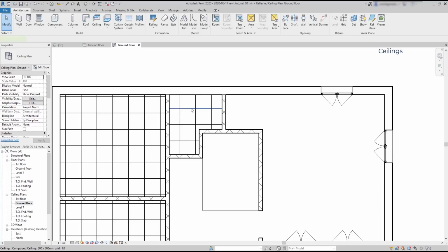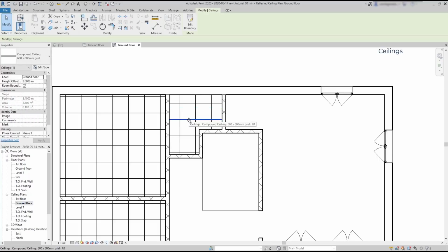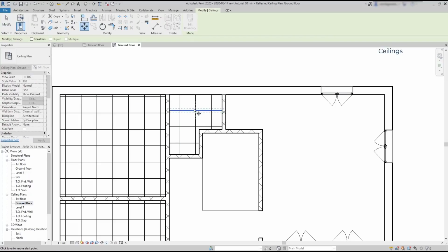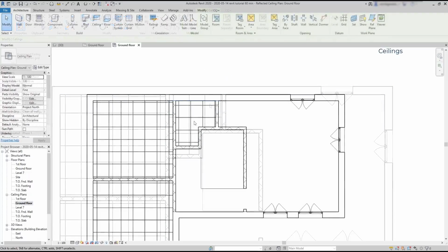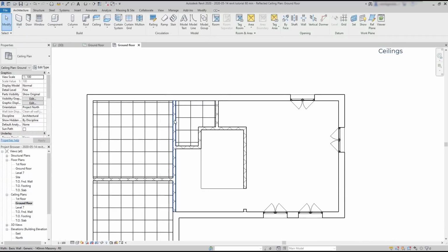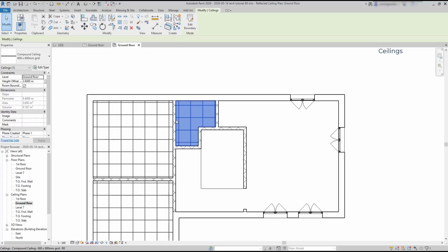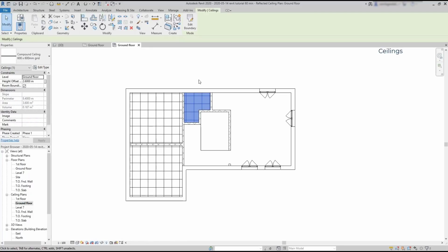These grid lines are useful to place elements on the ceiling, for example lights, but that's something we will focus on later. Now, to select the ceiling, place the pointer on a boundary line, then press tab several times until you find it. Then click. Now, to select the other two, I can repeat the same process, holding Ctrl when I click to select the ceiling,